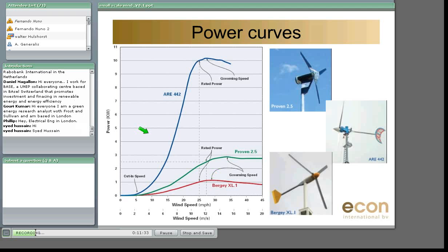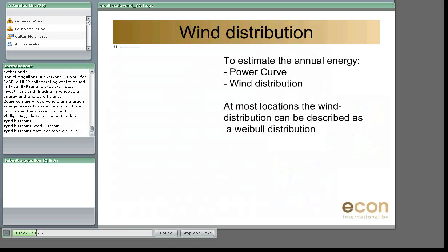So I think it's very nice that you know that between the cut-in speed and the rated power, you will not give your full output, and between the rated wind speed and the cut-off speed the turbine will produce the rated power. You will also see that between zero and the cut-in speed, you will not have any power. So basically, when you want to buy a turbine, you have to make sure that you know something about your wind speed and your location.